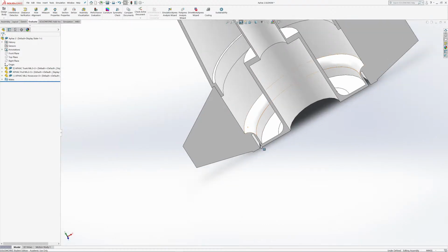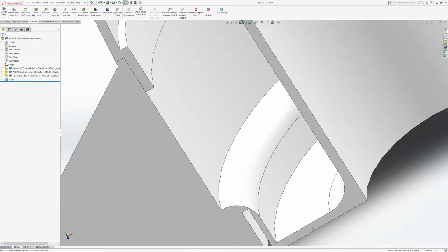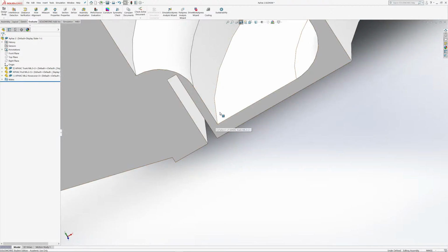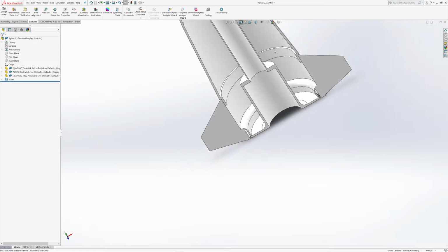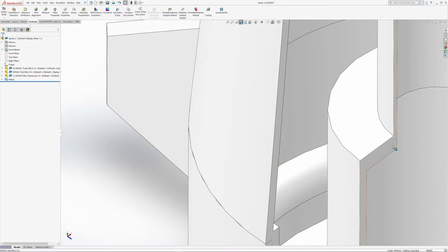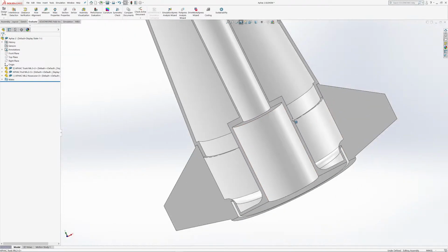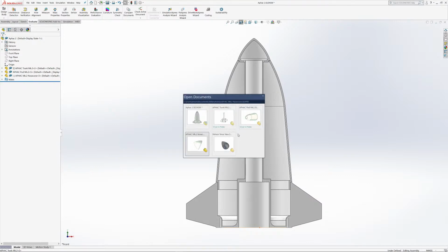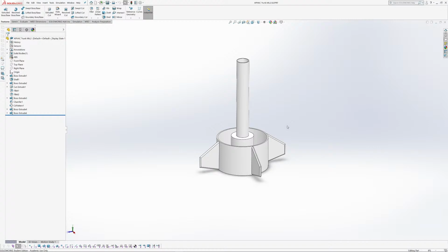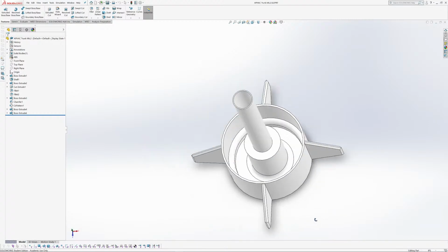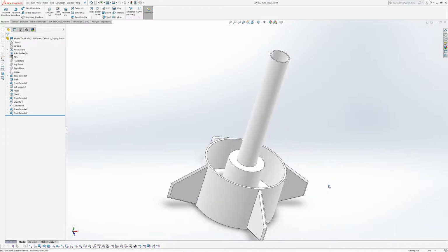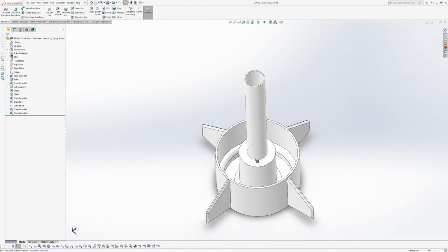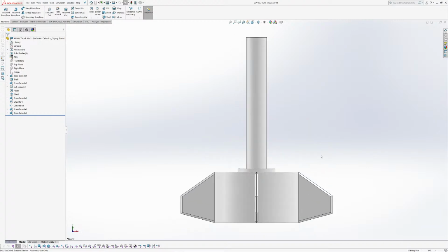So we're probably going to increase that a bit by either moving this distance out more or making this fillet less, probably a combination of both, because I think this fillet's a bit overdone here. And then I'd also like to add some additional strength stuff. I'd like to add a fillet here. Surprisingly, you may or may not know how things are 3D printed, but basically I will go over to the trunk here and you can see better. So basically this is the trunk, right? This is what we've got cut in half in the other drawing, and in order to imagine how this is going to print, we should look at it from this angle.